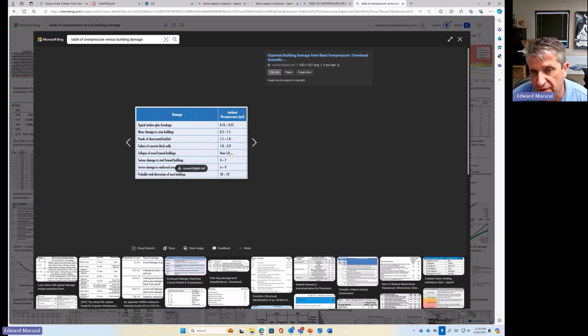Okay. Well, also the thing to think about in a pipe rack is, what are your leak sources? If you've got kind of seal welded flanges, a pipe rack is a very low probability leak source. So keep that in mind too. You're going to want to focus your detection on anywhere you have a lot of flanges or valving. Yeah, that's exactly the point. And also there is a high probability of corrosion, and we're putting corrosion monitoring as well, in order to prevent the whole thing. Yep. Thank you very much, Ed.